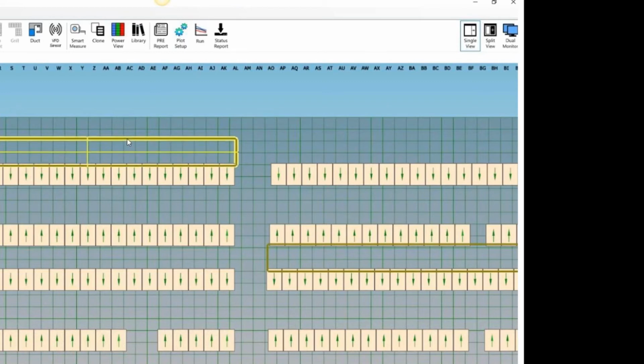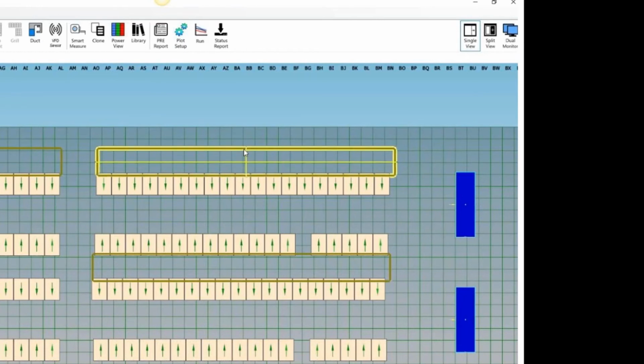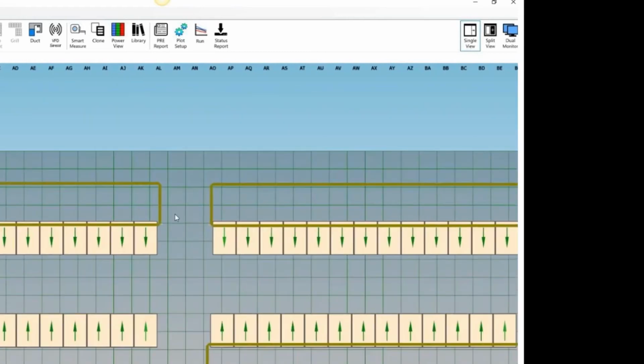So you see I move it in enough so that I can actually see the rack inlet in the top view, and that way I know it's going to be all right, and it'll just slice right through the rack and seal up everything around it. And I've got the containment in my buffer because I did a Control-C. It's in my paste buffer. So all I have to do is walk around the room and just Control-V it.